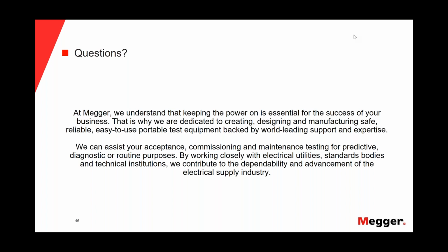Especially on the really old cables where you had unjacketed cable, where the neutral was in contact with the earth, the ground, you could have big trouble, like with any other dielectric type measurements on these types of cables. So if you have a jacketed cable, typically the condition of the neutral is good enough to get a good partial discharge reading.